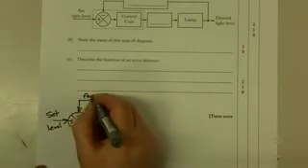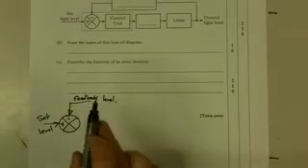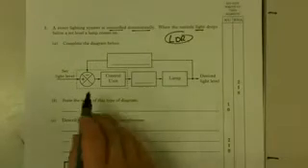Okay, you've got your set light level, so you can adjust the level of intensity that you want it to turn on and off at. So it's the set level, and this one is the feedback level. So there's obviously going to be something that measures light and then feeds back that information to the error detector. Let's have a look here. So this is the feedback loop.